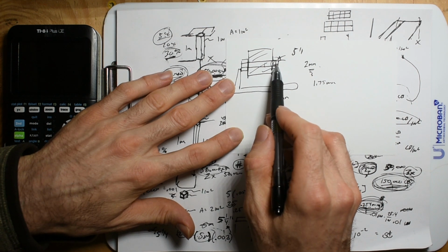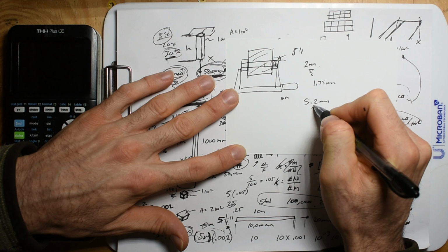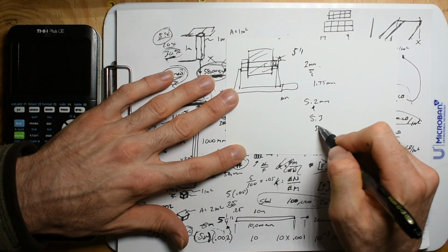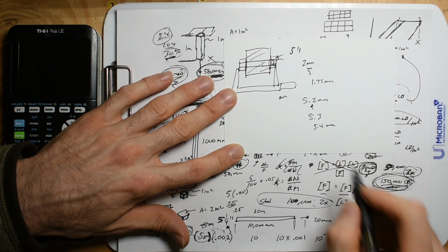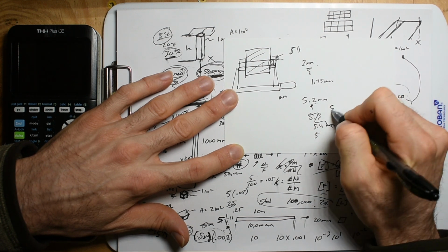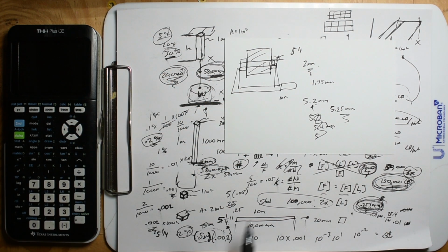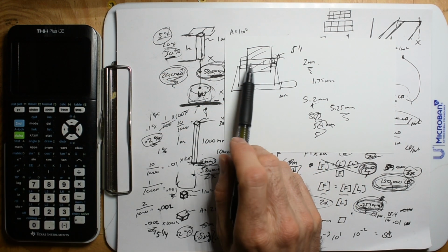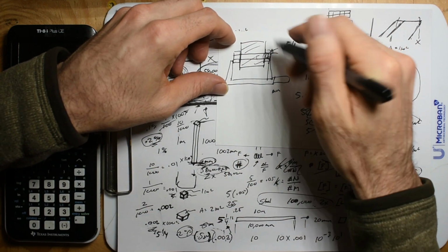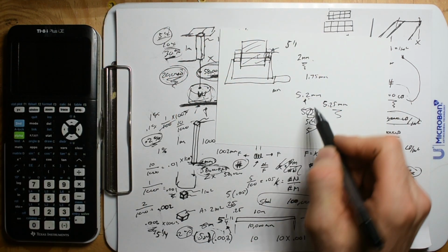After I tighten it, I really should just measure 5.2 millimeters. If I did that, that would be a perfect tightening, or 5.3, 5.4. I'm sorry. I chose 5.2 because we said 5.25 millimeters is the elastic limit on that. But there you go. So the next time I tighten a bolt, I can measure the length before and after. And as this nut is trying to lengthen the bolt, I can measure that.